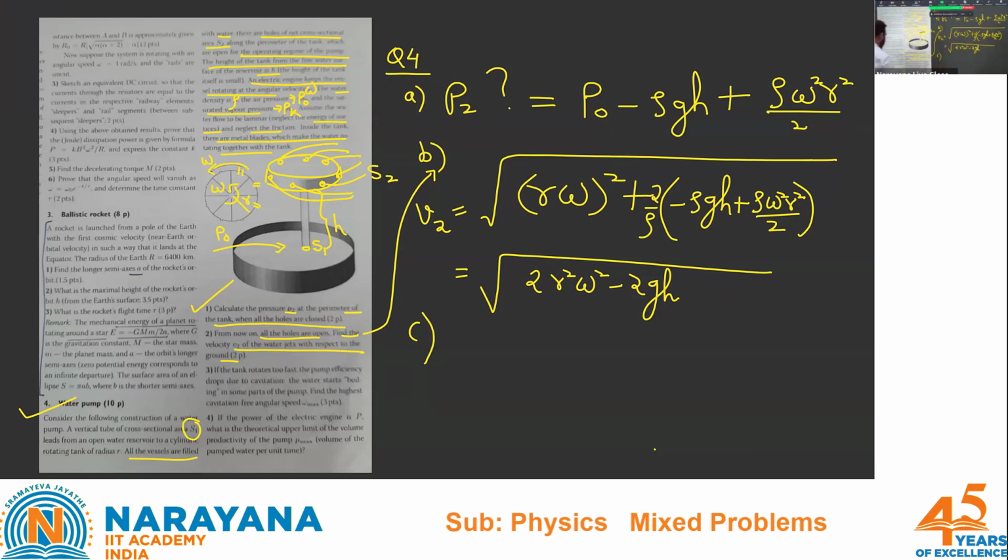Now comes the more interesting part, C part. D is in fact the best one. Now in C, he says, if the tank rotates too fast, the pump efficiency drops, and that is because of cavitation. So it's talking about something called cavitation. If you make omega very high, then it will cavitate. So what he wants you to do now, what is the highest cavitation-free angular speed? What is omega max? And that should be cavitation-free.